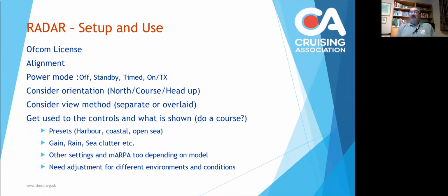So setup and use. Well, the first thing, and I'm aware people often overlook this, is that to have radar, you must have an Ofcom license. You must add it to your license for your boat with Ofcom to say you now have radar, because you are transmitting something. Second thing you must do, obviously after you've fitted it and run all the cables through, is make sure the alignment is correct. So make sure that when it thinks it's looking directly ahead, it actually is.